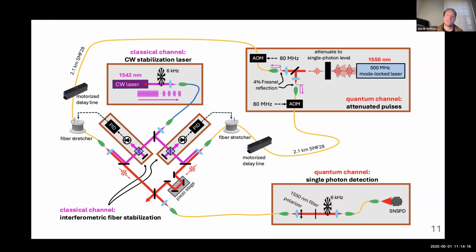So we could be doing something smarter and probably getting better results, but what I'm doing is basically just limiting the feedback bandwidth based on the chopper. I'm chopping at 6 kilohertz, which means I have to make it so that the feedback algorithm doesn't see changes faster than or on par with 6 kilohertz.